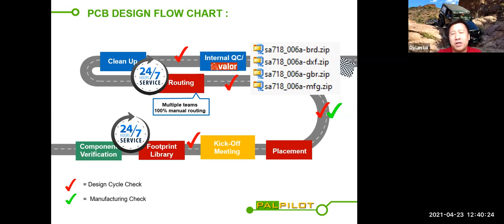And we pretty much know we'll reserve a space for the memory modules, space for the IO connectors, and space for any other technologies. Then we can group them beforehand, so we know this group shouldn't be set too far apart based on the schematic. And then we need to communicate from this group to the other group.